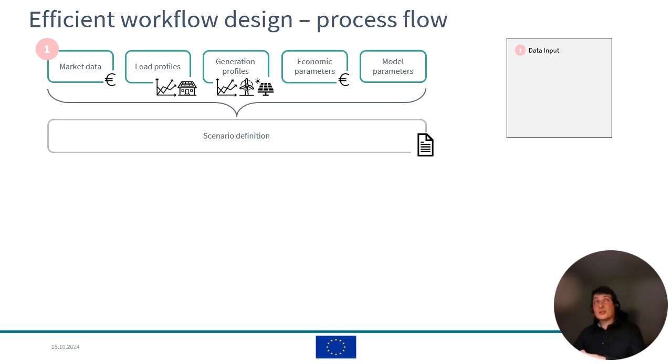So we are not only working with yearly sums of energy consumption, but we typically have 15-minute profiles of everything that we're simulating. Why 15 minutes? Because this is the billing period in electricity, basically. But we need profiles, of course.